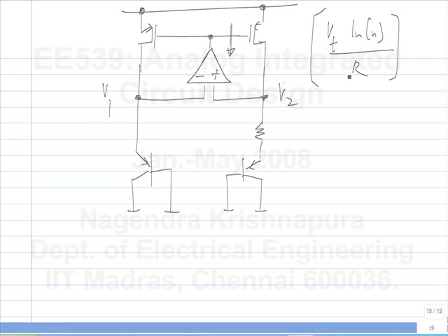Are there other possible bias points for this circuit? Zero. I mean, you can have all zero currents and nothing will happen. So we'll see how to get out of those situations later when we come to circuit design. Okay. So this is very useful because it generates a current that is proportional to absolute temperature, and it's known as a PTAT circuit.